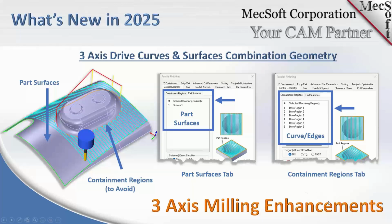Okay, so what we have here is 3-axis milling enhancements. So it's 3-axis drive curves and surfaces, a combination of geometry. In previous versions, you either did surfaces or you did curves. If you were doing curves and you wanted to get the same outcome, you would have to select all of the curves around the edge of the surface, then all the curves around here, and it would figure that out and cut between them. So now it just makes it a lot easier if you're going to avoid features like this in 3-axis.